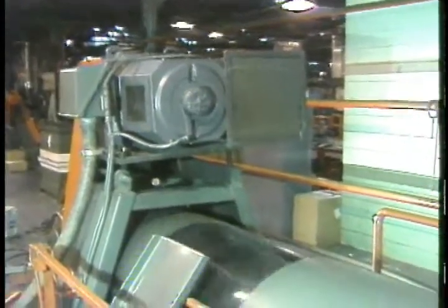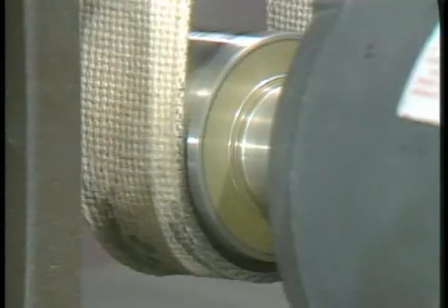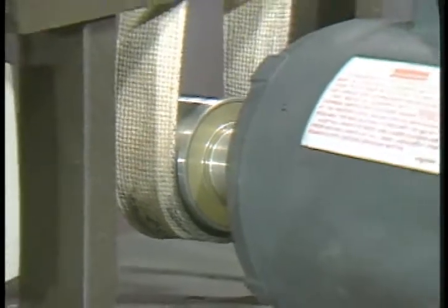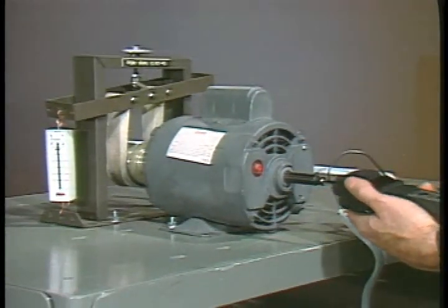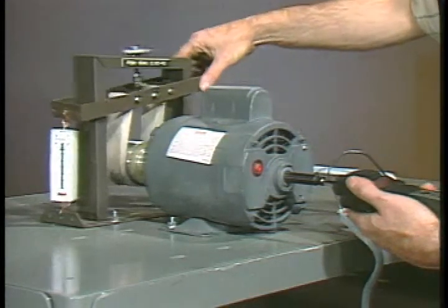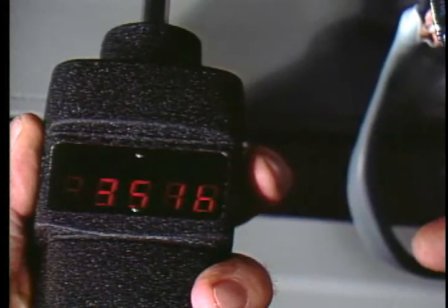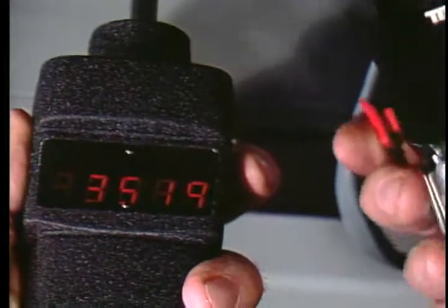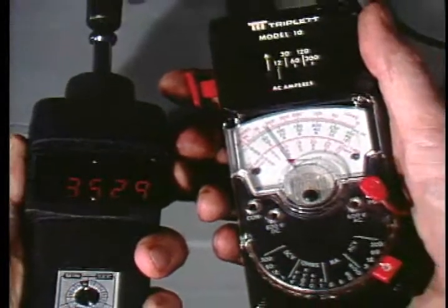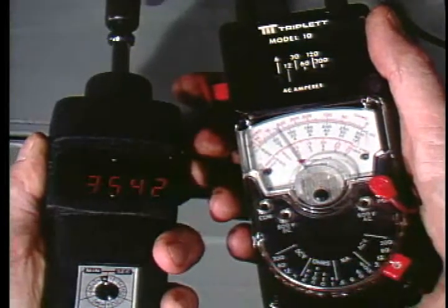Okay, we've seen how a motor is made so that current produces magnetic fields and how the magnetic fields produce torque and horsepower. Now let's take a closer look at the general operating characteristics of motors, how they behave under various load and speed conditions. We'll start with a motor running under no load. The shaft is turning freely at full or maximum speed, usually somewhat faster than the speed stamped on the motor nameplate. As you can see, even an unloaded motor draws some current. That's because the motor must overcome bearing friction and the wind resistance of the spinning rotor and fan.